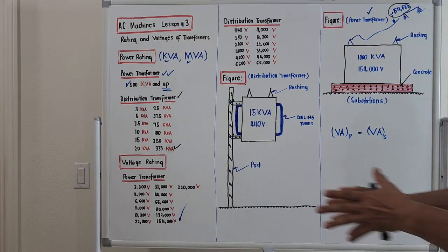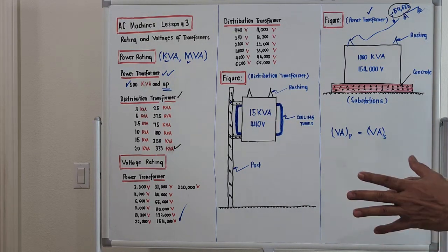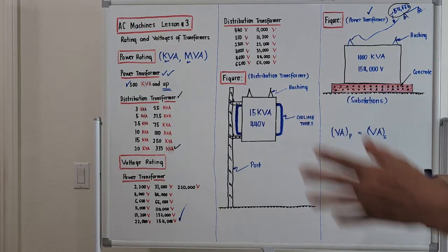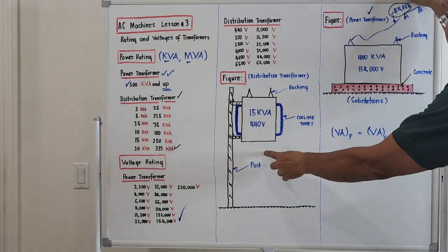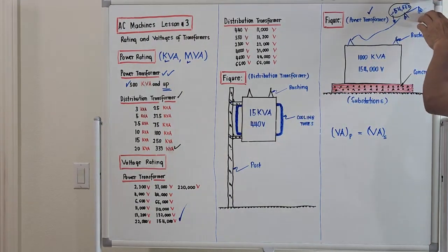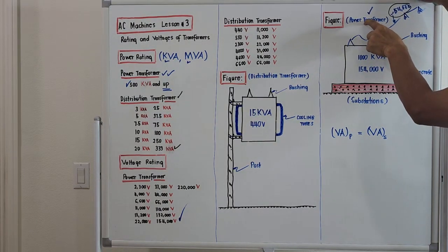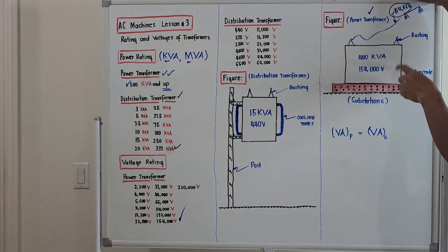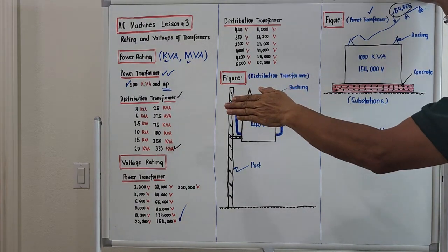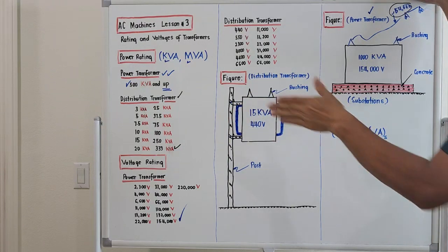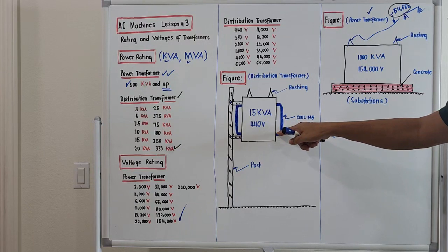So this could be distributed in the primary lines and secondary lines. And on the secondary lines, that will be the work of the distribution transformer now. Right? Coming from the power plant transmission line, it will pass to the substation through a power transformer. The voltage will be stepped down here. The step down voltage will be fed to the primary line, and it will be fed again to the so-called distribution line, or distribution transformer.